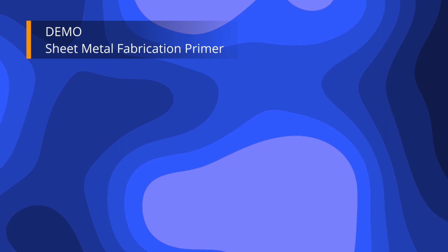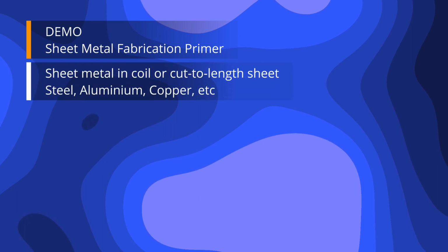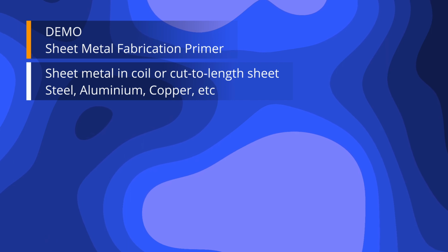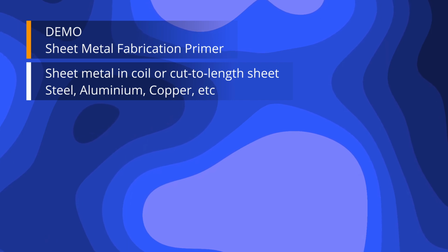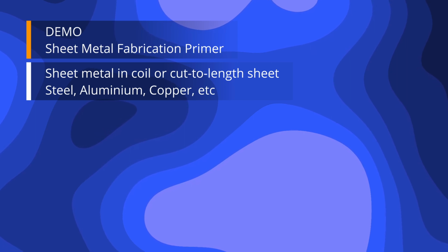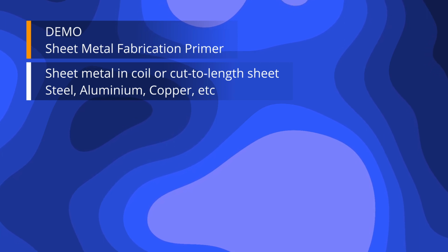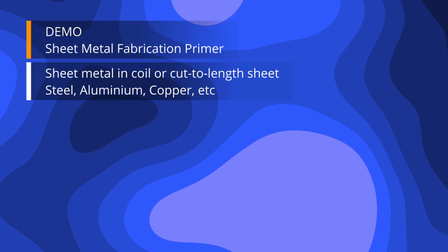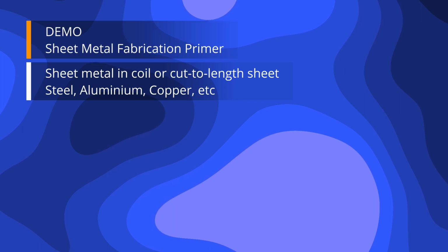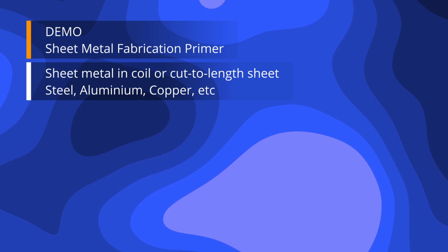the cost structure later. The main raw material used in stamping is sheet metal, usually in the form of galvanized steel, but mild steel, stainless, and aluminium are also quite common. The sheet could be supplied as cut sheet or coil, but this depends on the capability of the machine and the die design. In most cases, only a single sheet is used to produce a finished product, but it's possible that many types of sheet could be combined through a process known as clinching, which we'll need to factor into our cost structure.